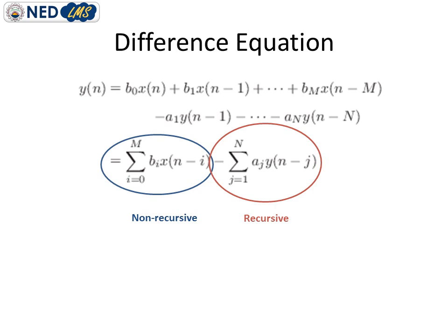Why am I saying that this particular expression belongs to an infinite impulse response system? Because in this equation you can clearly see we have the previous output, or some feedback, in terms of the delayed version of y of n. So as this equation depends upon the previous output samples, or in other words has some feedback, this overall equation is the generic form of difference equation for IIR filters.